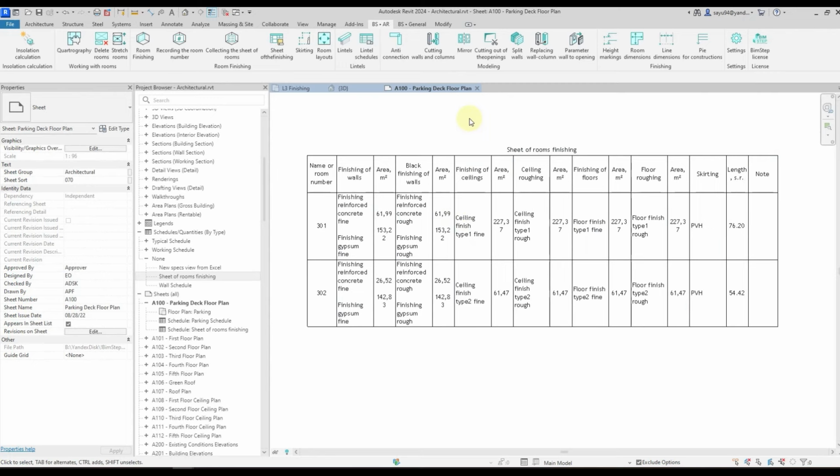To summarize, using the set of plugins to shape the finish rooms, you'll be able to model your room finishes depending on the type of surfaces to be finished. Then, with the skirting board plugin, you will be able to calculate the length of the skirting boards without taking into account the doors by room. And with the rest of the plugins, you can get to the formation of the room finish sheet in certain categories: separate walls, separate floors, separate ceilings, or form a sheet of room finishes where within rooms you have written all the finishing elements being inside.